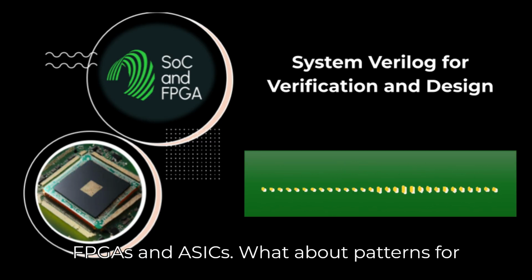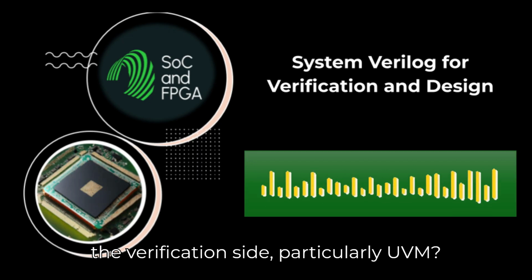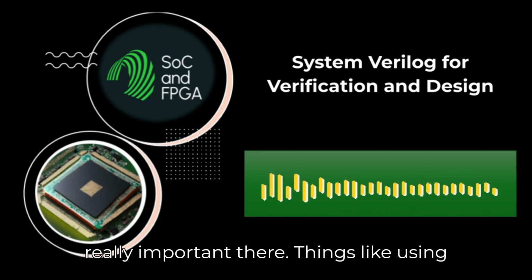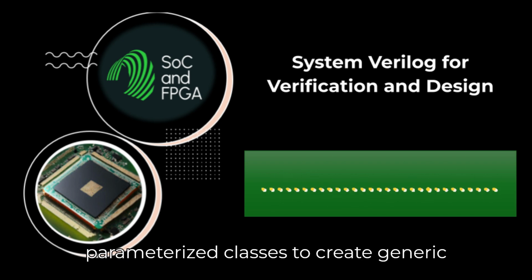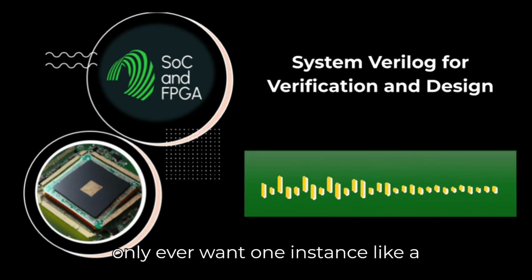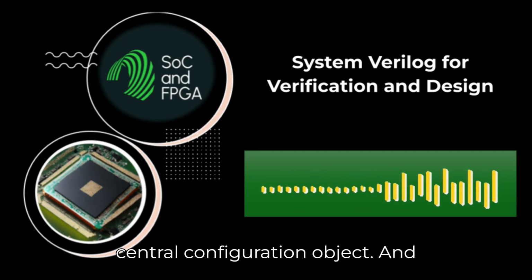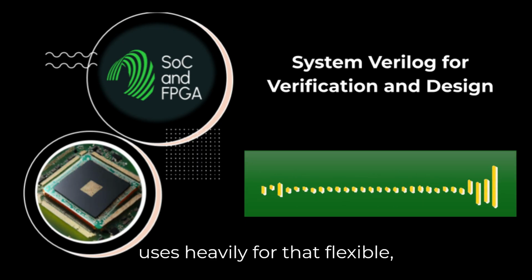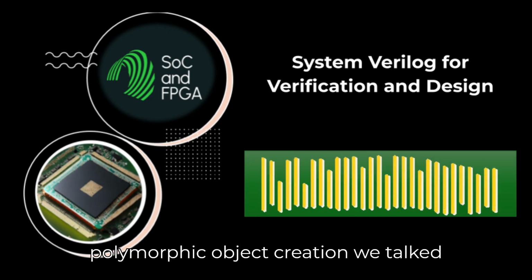What about patterns for the verification side, particularly UVM? Standard OOP design patterns become really important there. Things like using parameterized classes to create generic components, like a generic scoreboard. The singleton pattern for objects where you only ever want one instance, like a central configuration object. And definitely the factory pattern, which UVM uses heavily for that flexible polymorphic object creation we talked about.